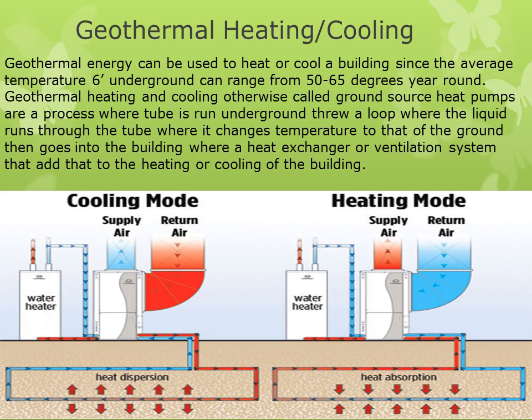water heater. Since the temperature below the earth is constant, you can start off with 50-degree or 60-degree water instead of the normal intake water temperature, which would be around 35 degrees during the winter, and during the summer you actually add heat to the water to take that heat away from your system, in turn cooling your system. That can add as much as 80% savings over other heating sources.